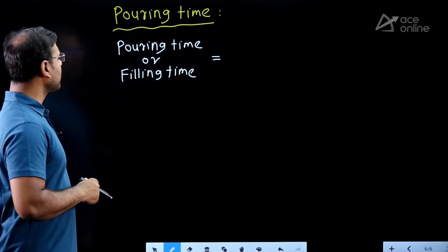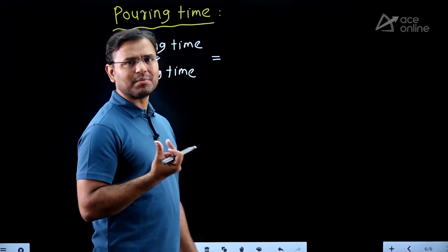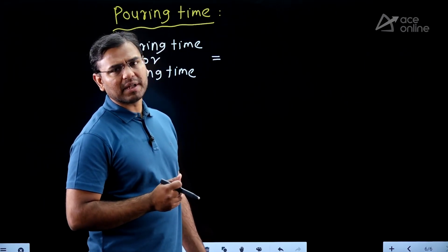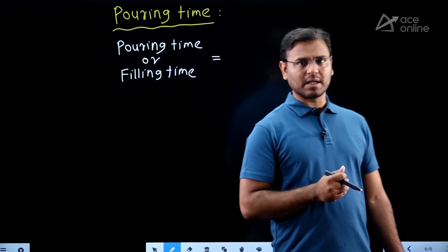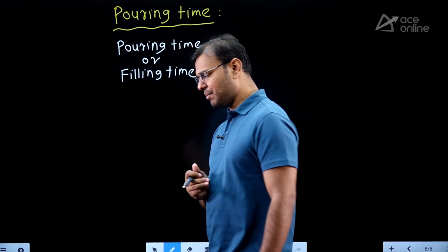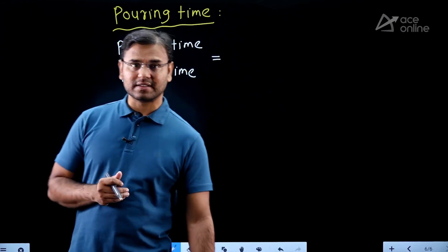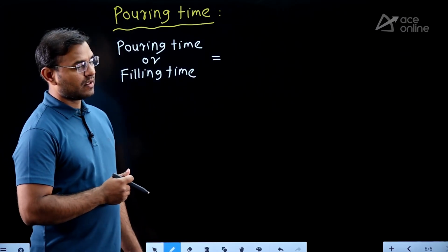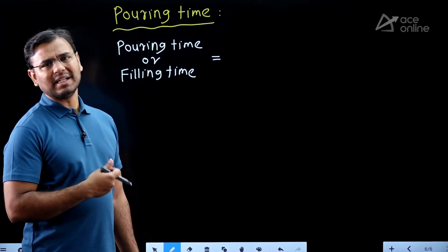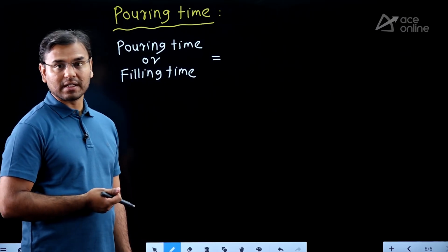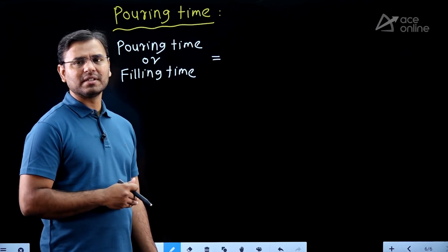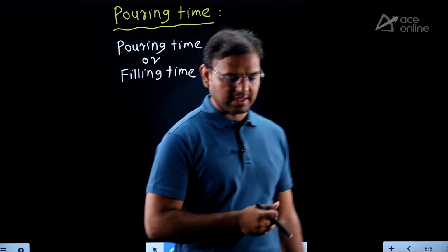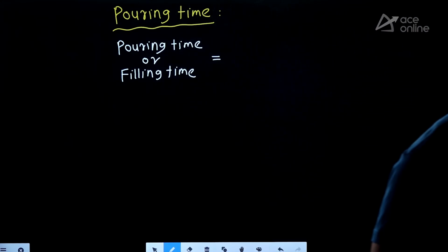Guys, you know that we pour the molten metal at the pouring temperature. In the metal casting chapter, in our theory lectures, we took one example: for iron, the melting point temperature is 1539, but we give some extra temperature, known as the degree of superheat, which is 150 to 200 degrees centigrade.